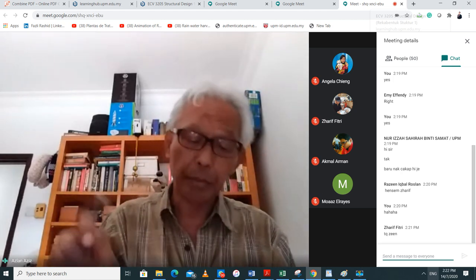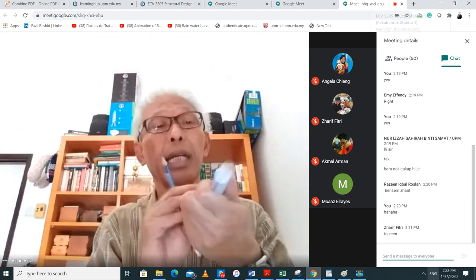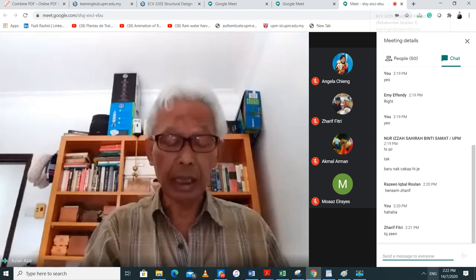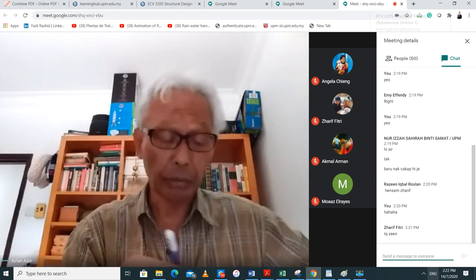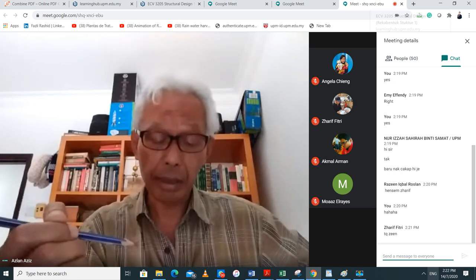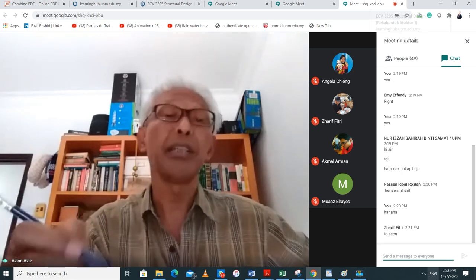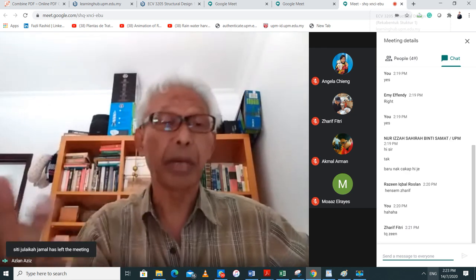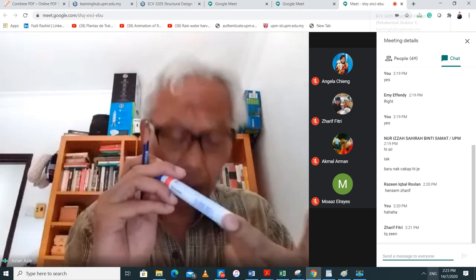Now, if the pile is circular, like this one here, then the surface area of the shaft would just be pi B D, multiplied by F sub S, and A tip multiplied by Q out. A tip, if it is circular again, is just pi multiplied by the diameter squared of the shaft divided by 4.